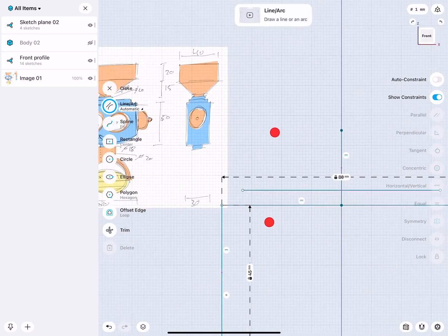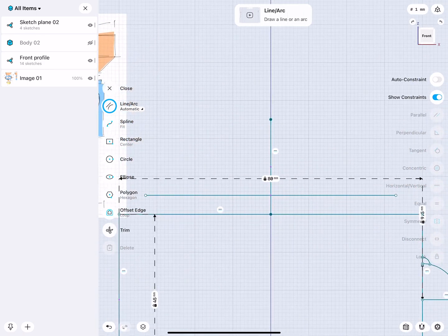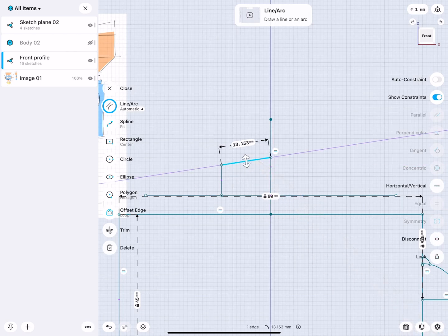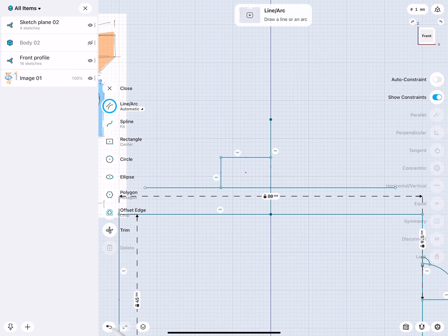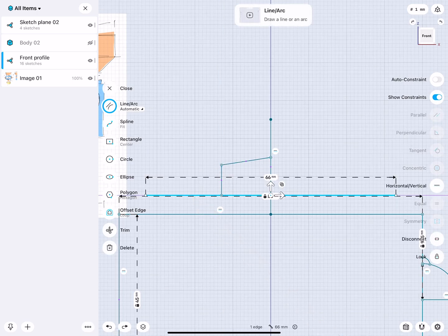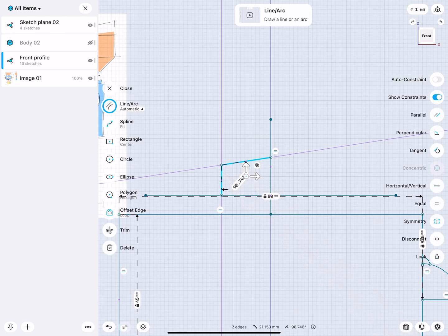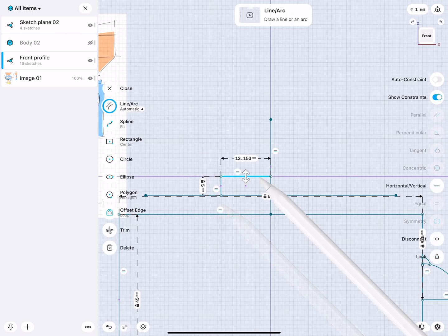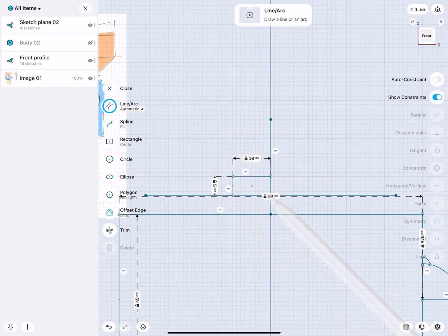And now it's very easy. We set 5mm, it goes up, and it should be 20mm. Careful about snapping to your midpoint, horizontal, vertical. Oh, this one line moved up, which we projected, so let's lock it. This should be 5. This should be 10.